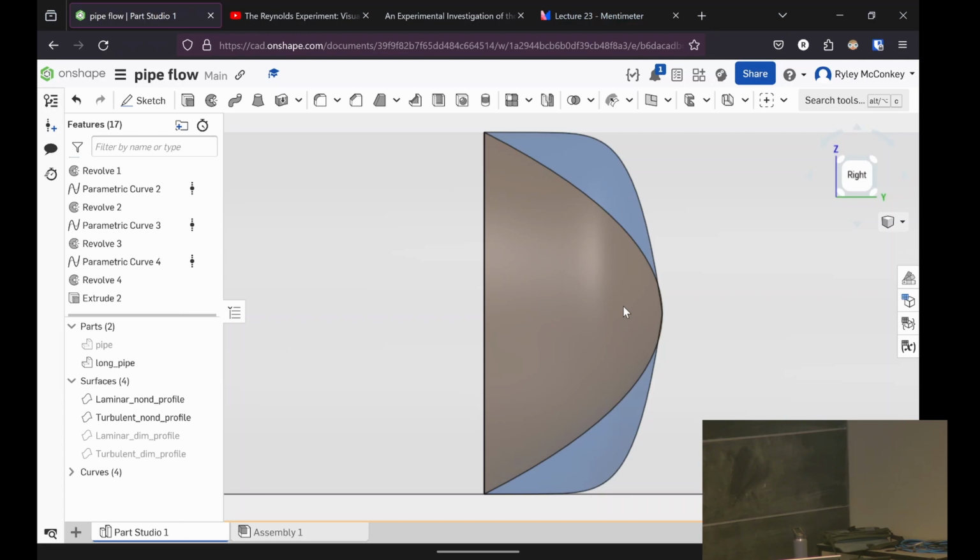That's a very good observation. The question is, why don't you get a very small boundary layer and then a big uniform flow in the middle, in internal flows, for pipes? For the laminar case, as we're going to see later today, the fully developed profile forms when the boundary layers on the top and the bottom connect. So you get this fully developed parabola. In the turbulent case, there's less connection between the boundary layers, but it still happens. That's why the turbulent case, with that 1/7 exponent, is still quite uniform in the middle section. For higher turbulent cases, it gets even more uniform in the middle, but you get a lot of wall shear stress. Does that answer your question? Yeah. Okay.